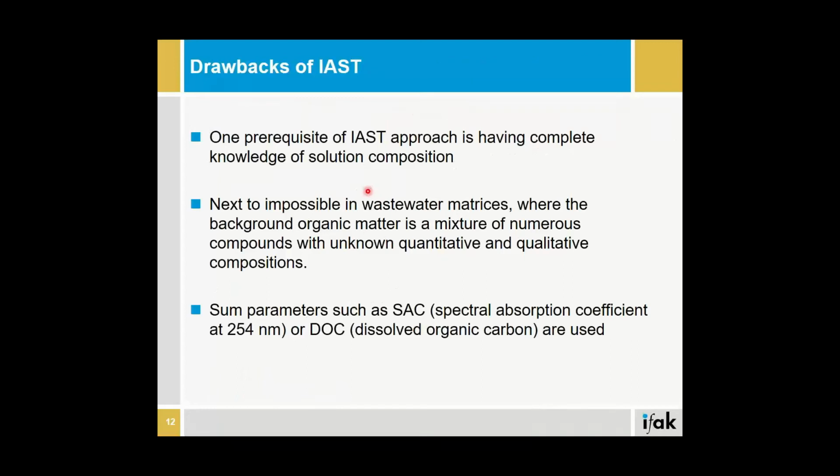However, we said IAST is best, but it's not perfect. One prerequisite of IAST is that we must have a complete knowledge of solution composition. So I have to know exactly what is inside my wastewater, by quantitative and qualitative composition. I have to know the isotherm parameters, and I also have to know the concentrations.